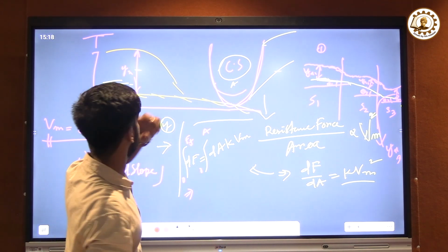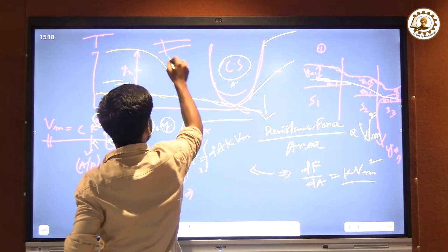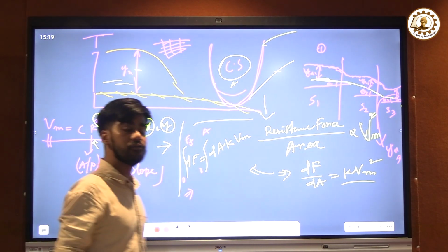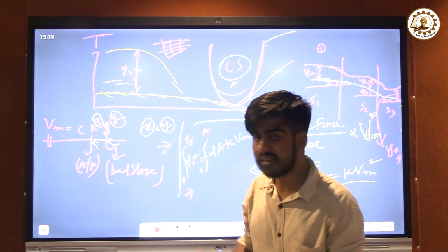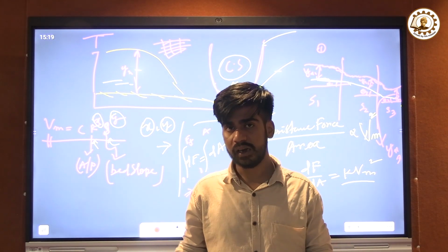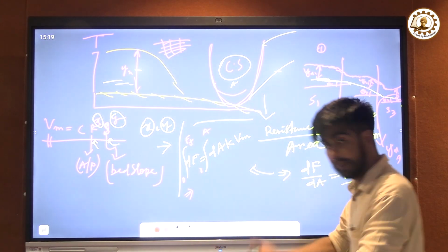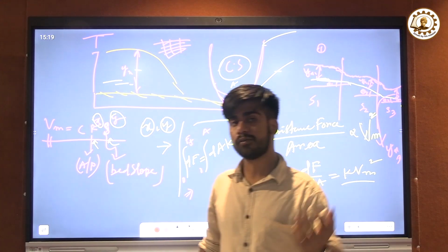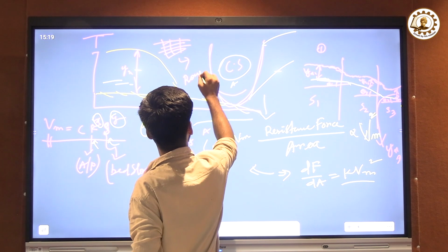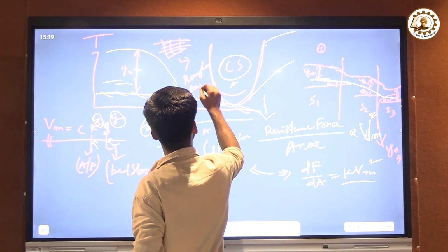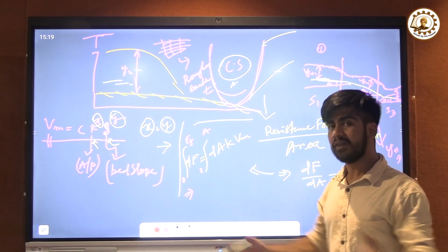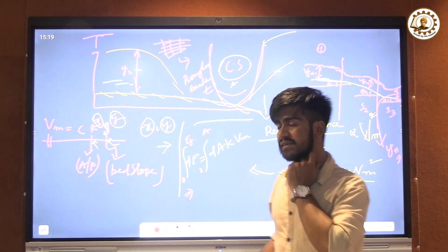Now one thing: the side wall or the bed has a particular roughness coefficient or friction coefficient. Due to the roughness, the more roughness I have from the side wall or the bed, the more resistance force I will get from this surface area. Then a roughness coefficient is used, so we can derive the total frictional force given by that particular surface area.